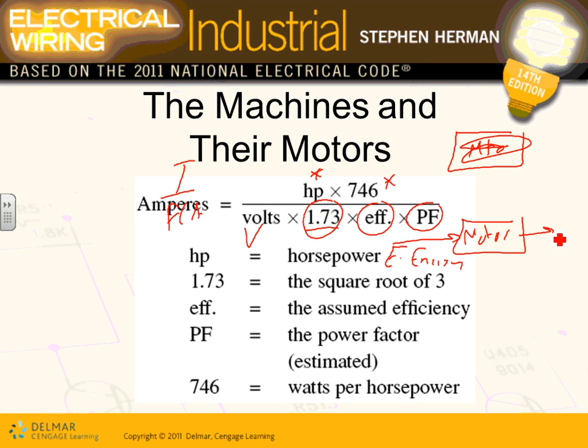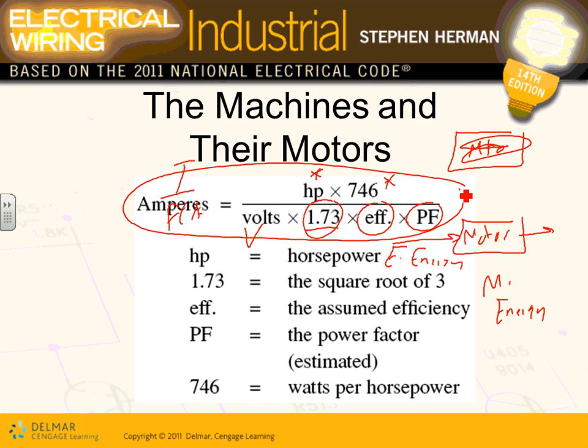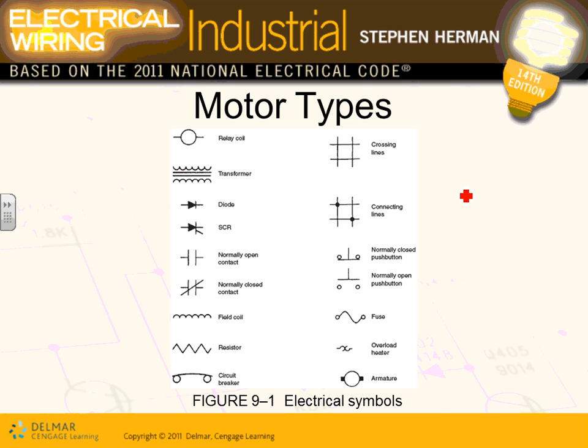And you get out of them mechanical energy. That's probably the beauty of motors. You get electrical energy into them, and out of them, what do you get? Mechanical energy. You heat and cool the building, you ventilate the building, you cut through 2x4s, and so forth. So this formula, please be aware of it. This will give you the full load current based on the mechanical horsepower for your system.